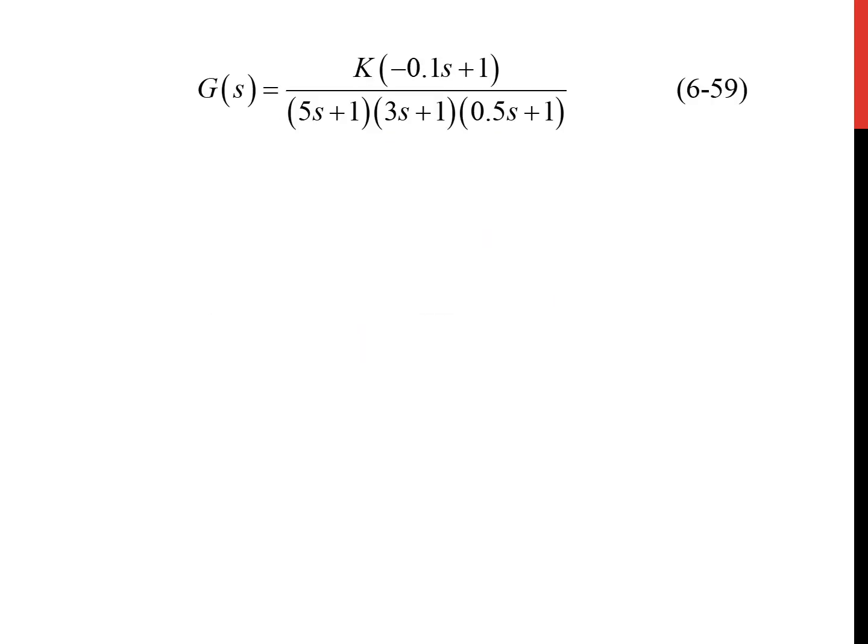So how do we apply the Skogestad half rule for reducing the higher order transfer function? In this case, you have the original transfer function as the third order. Our objective is to convert this into G approximate as K exponent negative TD s over tau s plus 1.